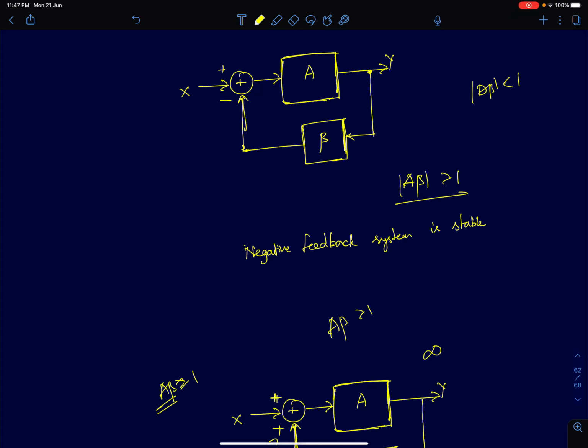Hi everyone. In the previous two lectures on the course Microelectronic Circuits, we discussed negative feedback amplifiers and how to find loop gain in a negative feedback circuit. While discussing some examples on how to find the loop gain, we took an example where we encountered a positive feedback circuit. And in that circuit, we spoke about stability and we said that for that circuit to remain stable, the loop gain should be less than 1.